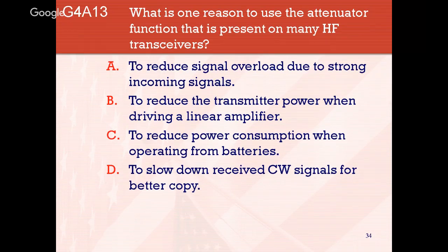What is the one reason to use the attenuator function that is present on many HF transceivers? Remember, you want to attenuate signals that could be very strong, overloading your front end on your receiver. So basically, it works to reduce the signal overload due to strong incoming signals.